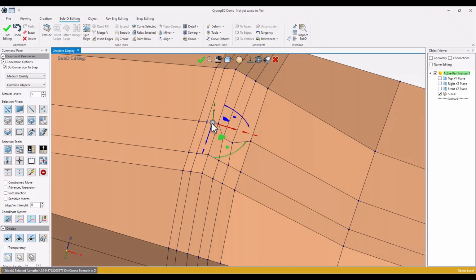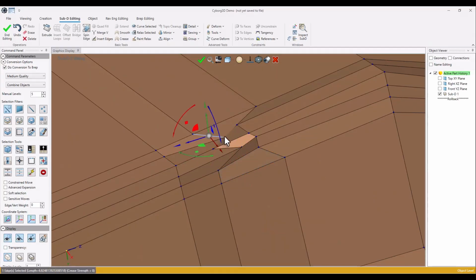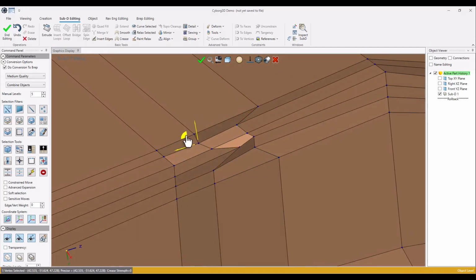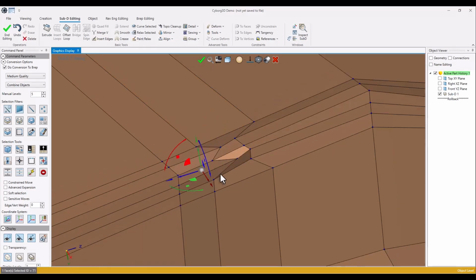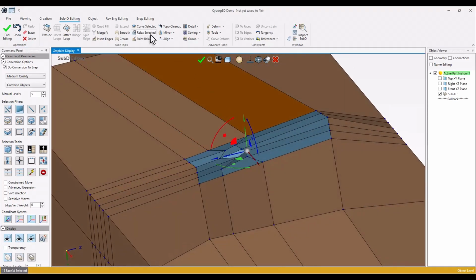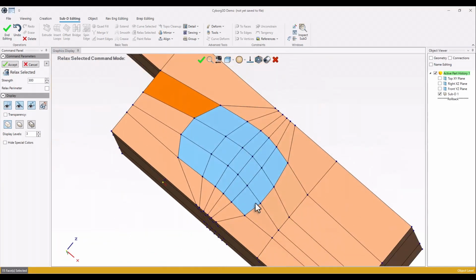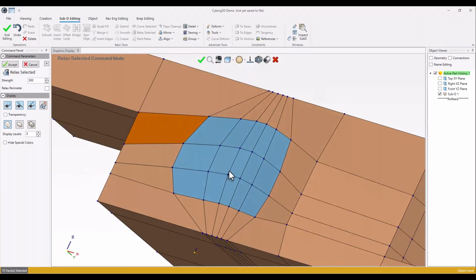When you've got some messy vertices and edges, rather than just go ahead and move them with your hand manually like this, we have a tool called relax selected. The faces you just wanted to relax here, maybe those, and click on relax selected, so it's just giving you some relaxation to the nodes.